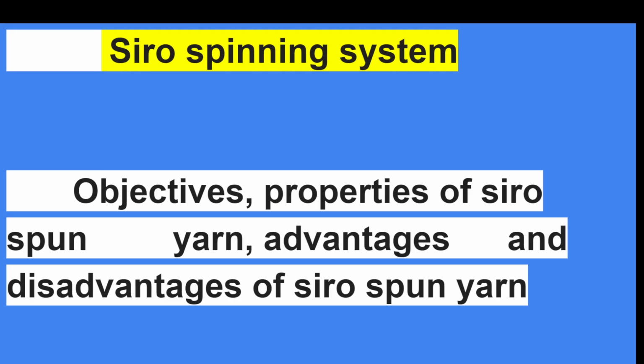It means the yarn received directly from a ring frame on which the Siro spinning mechanism has been mounted can be used directly in the knitting process, and the yarn breakage problem gets resolved in the knitting process.